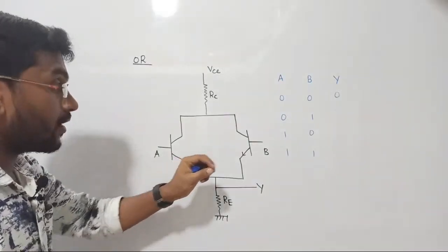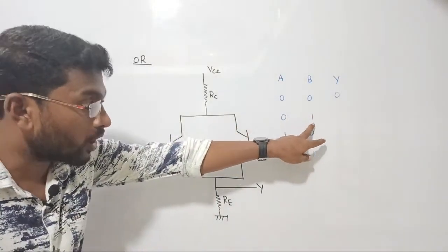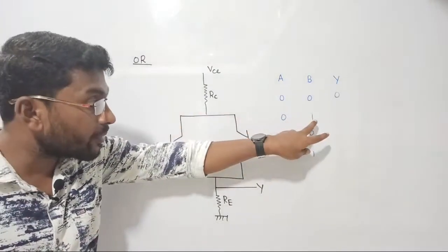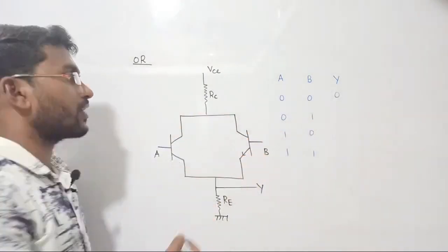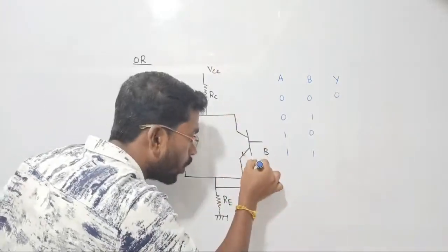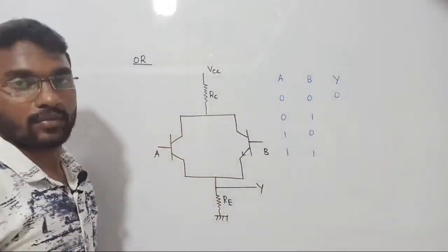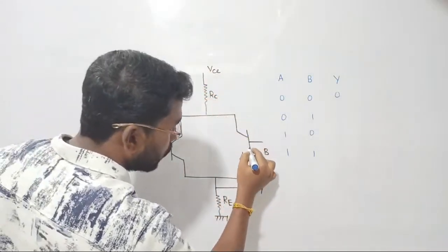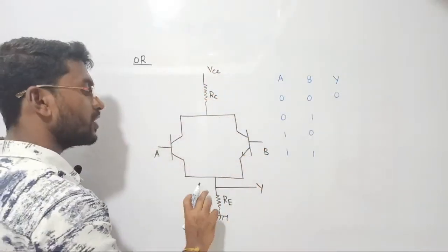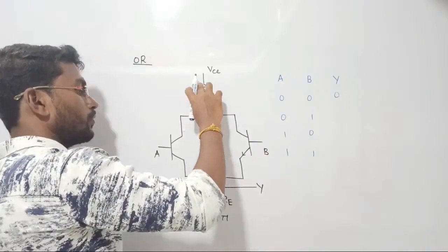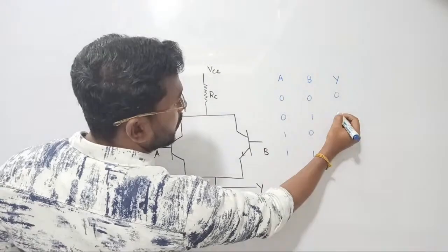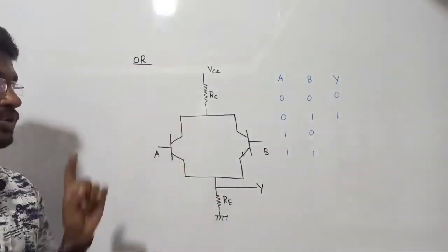When we turn on, there is transistor 1, B, that is A B. See, there A is 0, open circuit, but B is going to be turned on immediately. Once it is turned on, the supply will come here, go here, come here, and reach. Yes, there will be a flow, right? If you turn on this transistor, your current will flow like this. So there will be a little drop here, a little drop here, and definitely output will come. I am damn sure for that. So automatically you can receive output as 1.